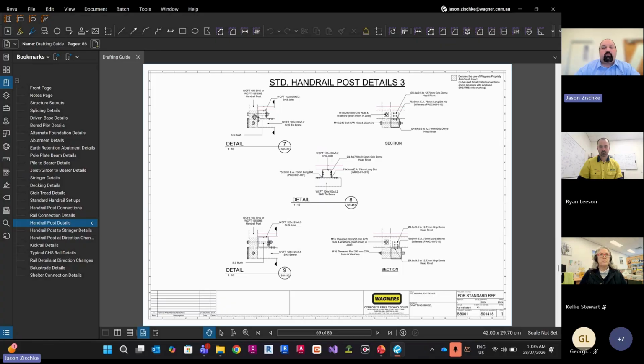So anything that makes jobs on site easier, where we do a little bit of prefabrication with our connections. We would generally drill the posts and tie braces here, and then we were able to get rid of the bolted connection from our joist to tie brace and bearer by further testing and development.